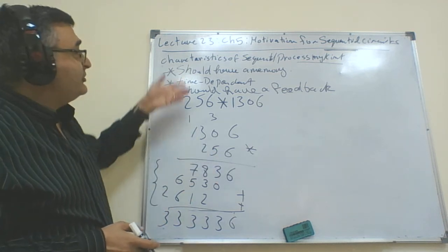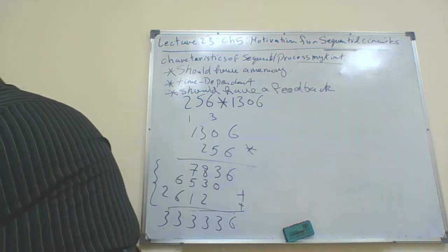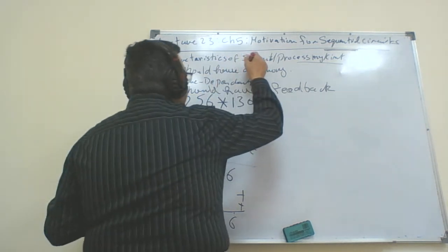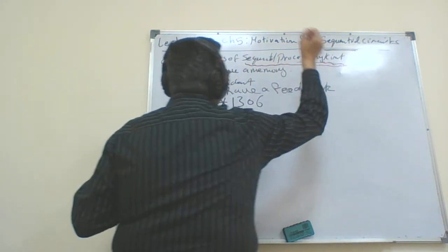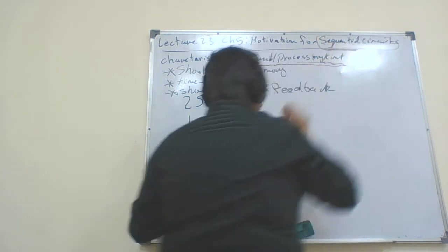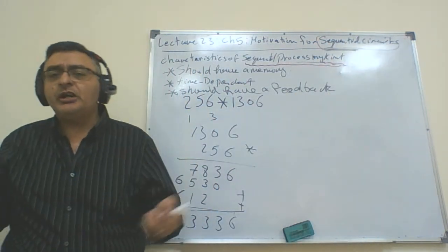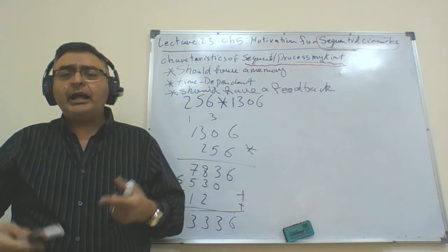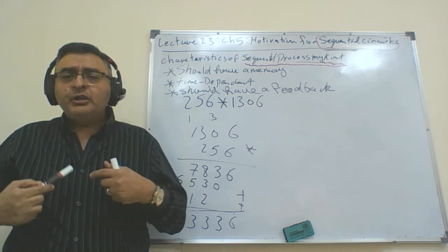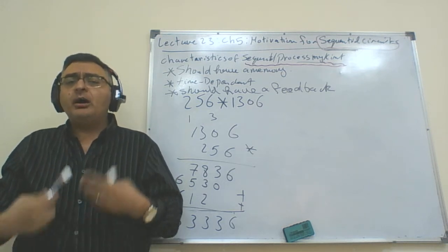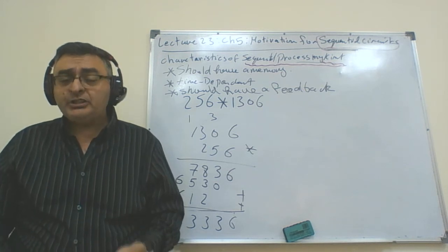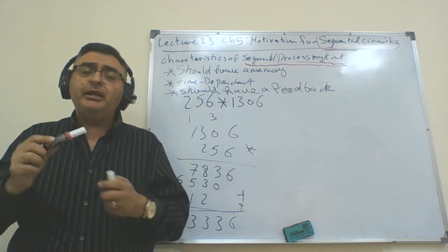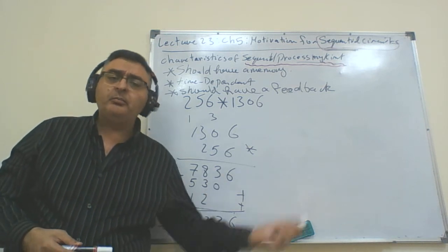So this is actually what characterizes the new systems or the new circuits that we are learning, which are called sequential circuits. Sequential circuits are digital logic design circuits, but they have to satisfy 3 conditions that allow those kinds of circuits to perform complex operations, hard operations, or operations performed on long numbers that we were not able to achieve easily in the combinational circuits.